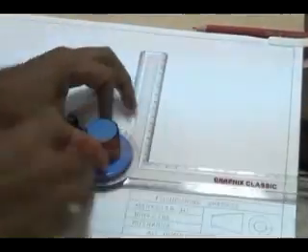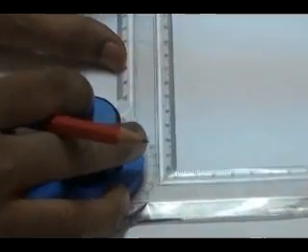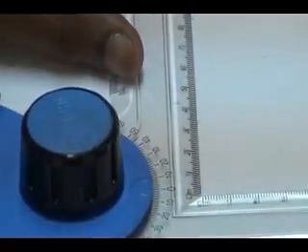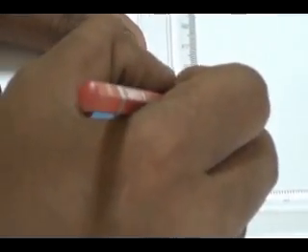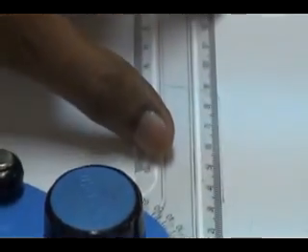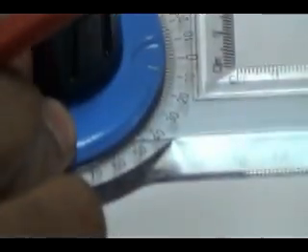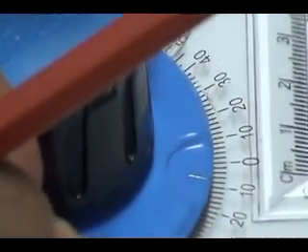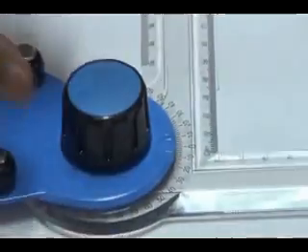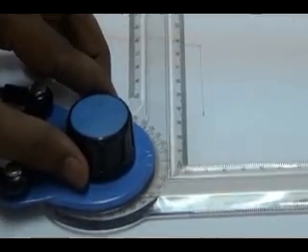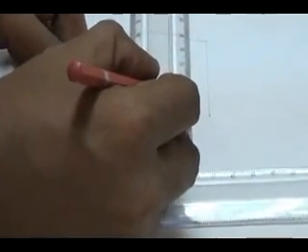Now using the same 2H pencil, I am connecting the last division with the other end. I am connecting the last division with the other end with a 2H line. Right. I am tightening the knob of the drafter. Now wherever I move my drafter, I will get a parallel line to that line. Wherever I move it along using that scale, if I draw, I will get a parallel line. So I am moving to the next division. Where it intersects the original line, there just I am getting the divisions. Okay, all the way I am not drawing the construction line. Right.